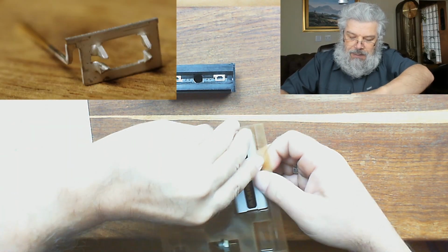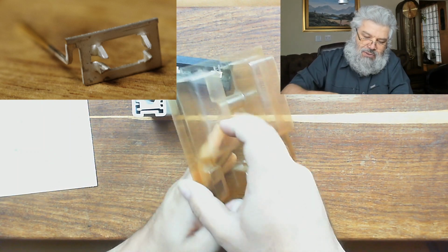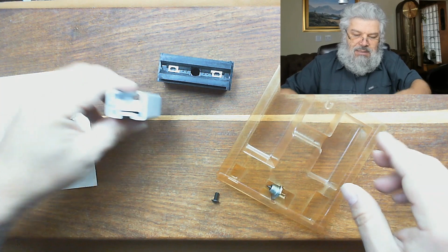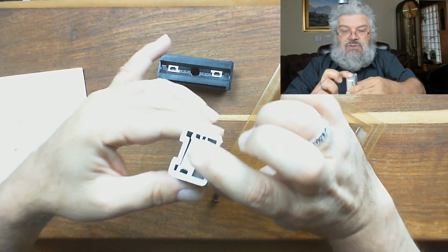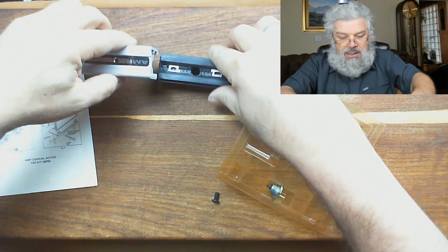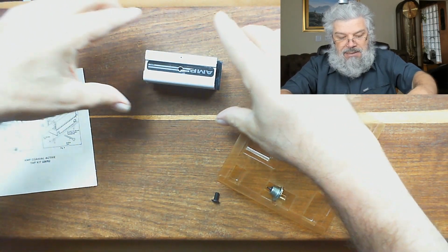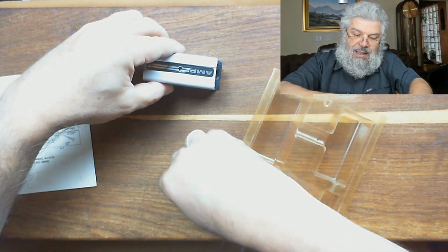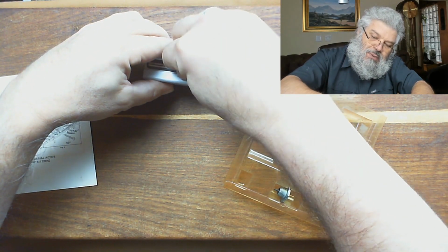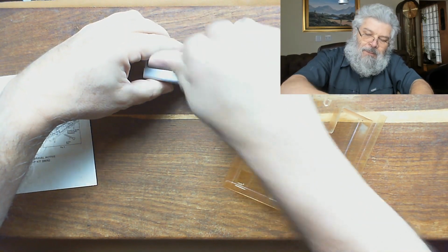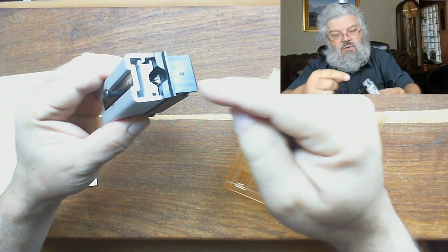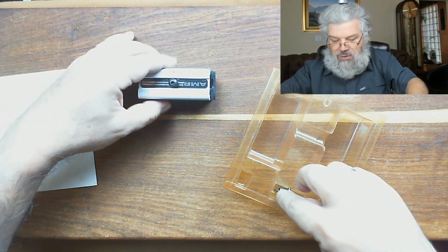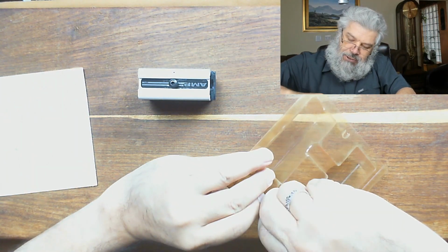Okay, there's an easier way to do this. There's the aluminium part. You can see it has a part that can move up and down, so it will push the cable into that bottom plastic part. It's going to slot over the plastic part like that, and then as we apply the screw, which goes into that little hole, it's going to push that down, and as it pushes it down, it will force the cable into the short teeth.